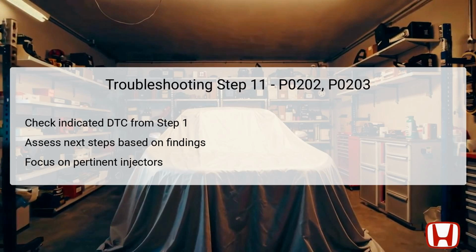Returning to the initial DTC assessment will help narrow down which steps to take following your previous troubleshooting. If DTC P0202 shows up again, it is a signal to advance to step 12 for further diagnostics. If not, then the issues may not relate specifically to these injectors, allowing exploration into other components or systems that may be contributing to operational problems.